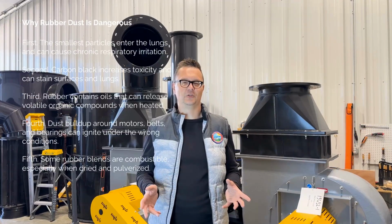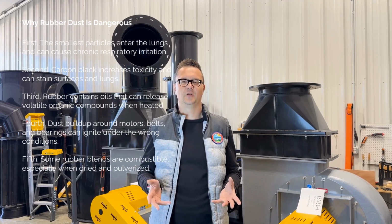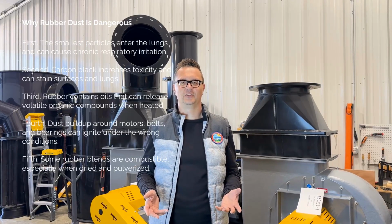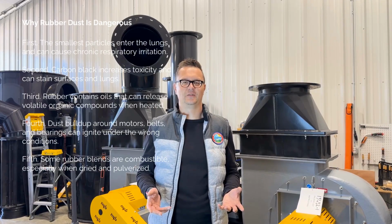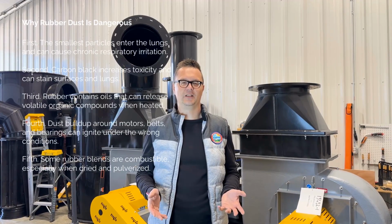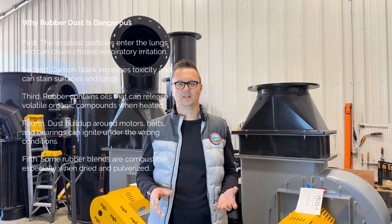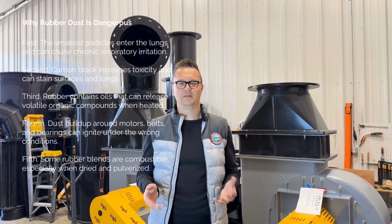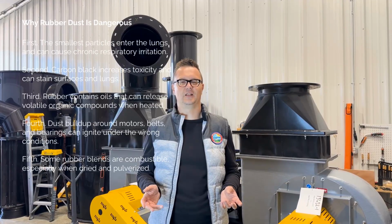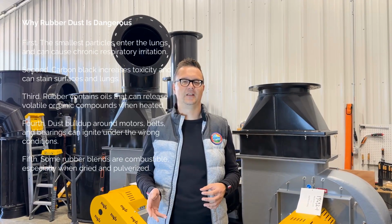Why rubber dust is dangerous. Rubber dust introduces multiple hazards. First, the smallest particles enter the lungs and can cause chronic respiratory irritation. Second, carbon black increases toxicity and can stain surfaces and lungs. Third, rubber contains oils that can release volatile organic compounds when heated. Fourth, dust buildup around motors, belts, and bearings can ignite under the wrong conditions. Fifth, some rubber blends are combustible, especially when dried and pulverized. In recycling operations, the combination of dust, friction, and heat makes proper air handling essential.